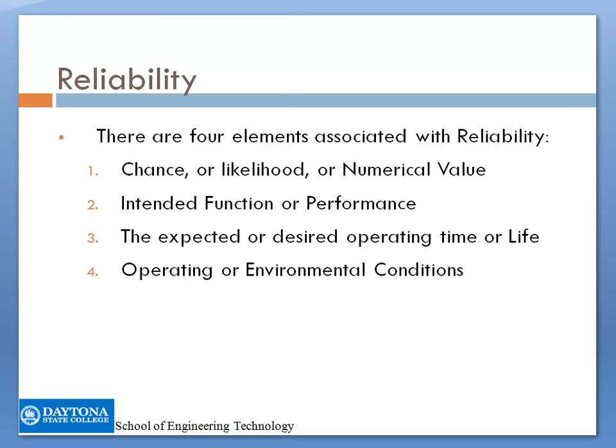And the fourth one is the operating or environmental conditions. You need to take into consideration that a product designed to function indoors would not last the same if you are going to be using this product outdoors. It will be exposed to sun, to the wind, to precipitation. So those different environmental conditions must be part of your reliability study.